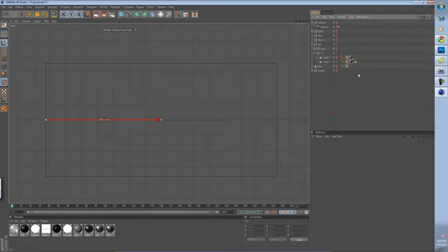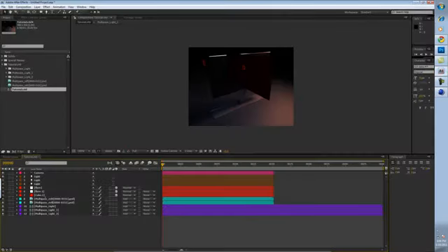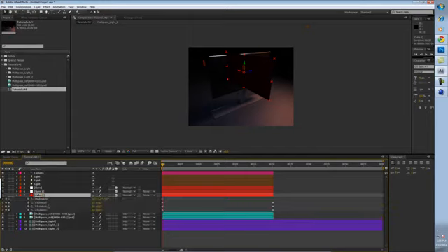And now if I just save the compositing project file, what I'll end up with is this solid in place. I can rotate it. If I press R, the orientation is automatically set to be keyframed, but I want to turn that off. So I'm just going to click on the stopwatch to turn that off.